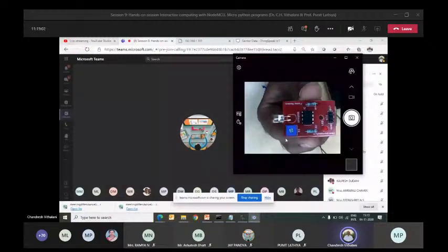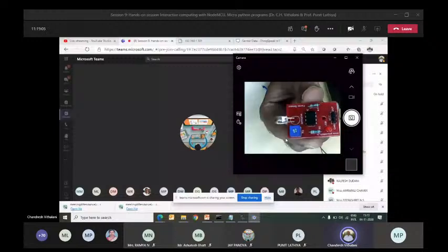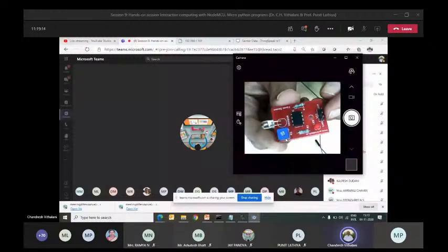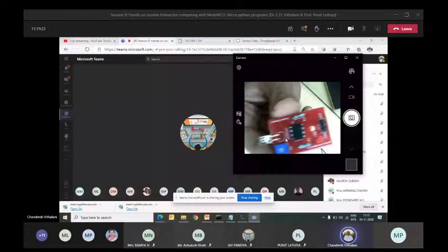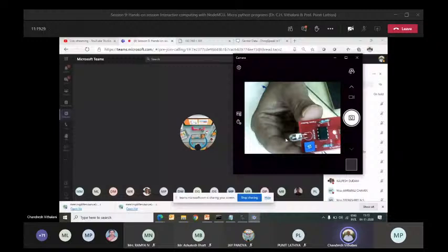This sensor will give you digital data. It also has 3 pins. Mostly all the sensors have 3 pins. You can see here there is an out pin, and in between there is VCC, and then the ground. So ground, VCC and out, there are 3 pins. This is a semiconductor device which will sense the flame. It will give us a digital data output. Digital data is very easy to read. So I will show you that program.